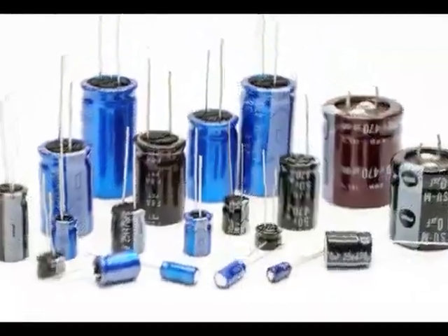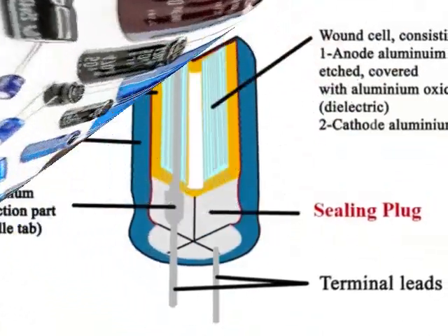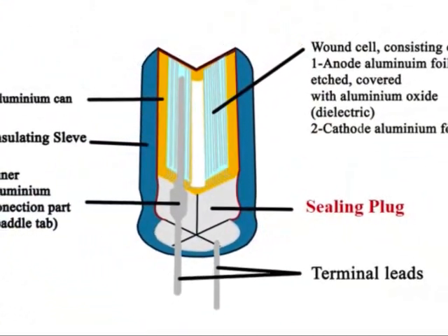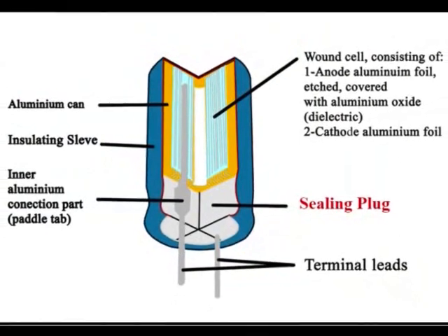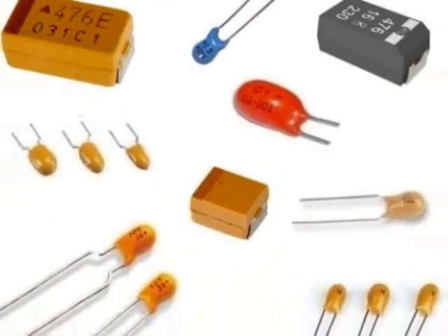In this type of capacitor, an oxide layer is used as a dielectric. Due to the thinness of this layer, the capacity of these types of capacitors is high. However, these types of capacitors have relatively high leakage and low breakdown voltage.